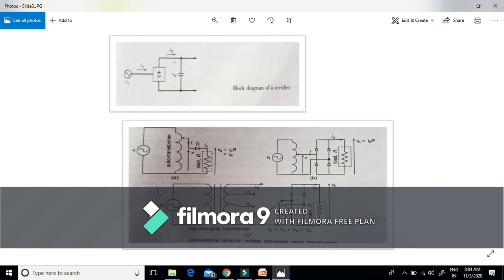We are using auto transformers or tap changing transformers to obtain that variable output voltage. But this suffers from the disadvantage due to the large size, weight, and cost of the transformers, resulting in an enormous amount of losses due to the use of this oversized transformer. And these disadvantages or losses are overcome by using power semiconductor devices like thyristors or the combination